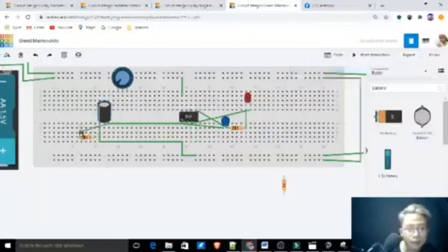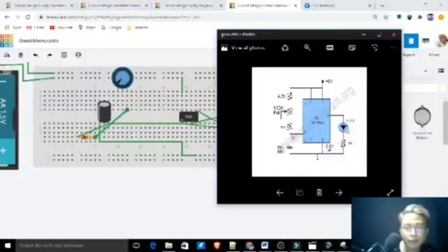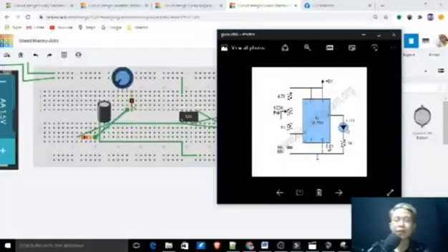So from here we have to connect this one here, this one here. As you can see, so here from pin 6 and 2 into the 1 kilo ohms resistor here, that one. So here to the 100 kilo ohms one, so the potentiometer, the 100k potentiometer.